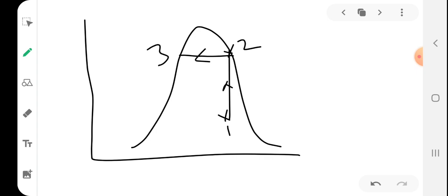No undercooling means, if there is undercooling, then point 3 will be after some more expansion, somewhere like here. Some more decrease in temperature will be there. But actually there is no undercooling, so 3 will be exactly in this position itself, and 3 to 4 will be like this, and 4 to 1 will be like this.